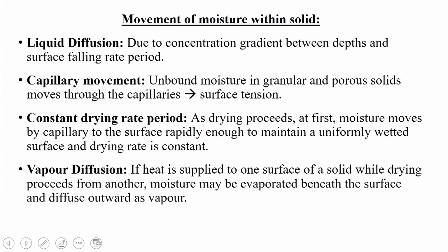Before going into the drying time calculation, we need to discuss an important topic: the movement of moisture within the solid. The first movement is liquid diffusion, due to the concentration gradient between depths and the surface; in the falling rate period, liquid diffusion takes place. Another movement is capillary movement, where unbound moisture in granular and porous solids moves through the capillaries, due to surface tension.